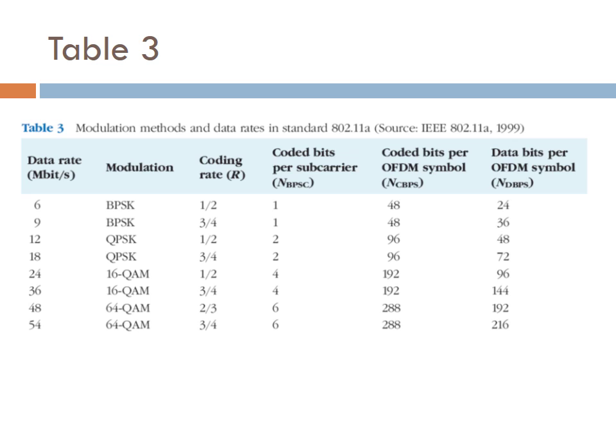You should now be able to appreciate most of what Table 3 is showing. Just a few points remain to be explained. The first point is one you will doubtless have realized already, namely that at different data rates, different modulation methods are used. This is also a feature of other wireless standards, where distance from the transmitter or noise degrades the quality of the received signal. The system drops down to a lower data rate and possibly a different modulation method.